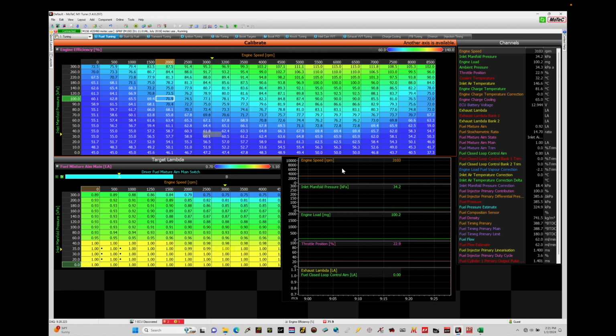Let's jump in here and take a look at where we can find our fuel injection timing programming, and we'll talk about some of the concepts and fundamentals of what injection timing represents, what we need to know, and then we're going to be utilizing an Excel spreadsheet calculator to further refine and figure out what values we need to actually place into the table as a starting point based around our camshaft profile that we're running in our engine. So injection timing will be tied into our intake and exhaust valve opening and closing events, which we can find the information from a cam manufacturer and populate that into our Excel spreadsheet.